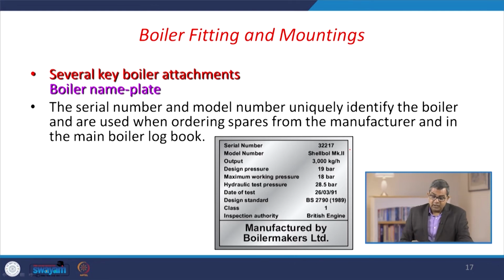Apart from this, you have the output, that is the maximum designed output, design pressure, maximum working pressure and hydraulic test pressure. All these things are essential for the safety aspect, because if you go beyond this hydraulic test pressure, or if you have reached the maximum working pressure, that gives a ceiling beyond which you cannot go, otherwise there may be certain safety issues pertaining to it.